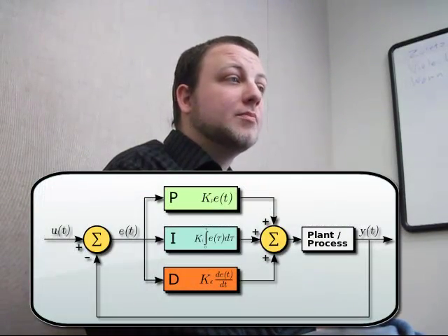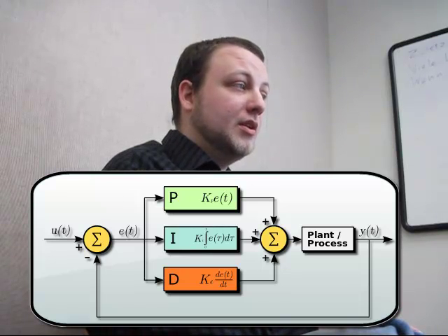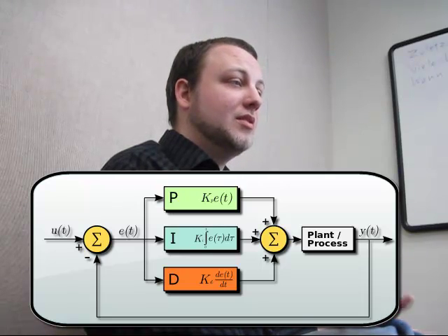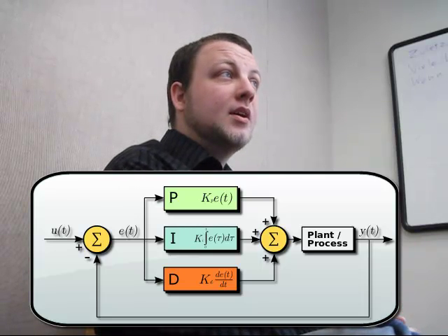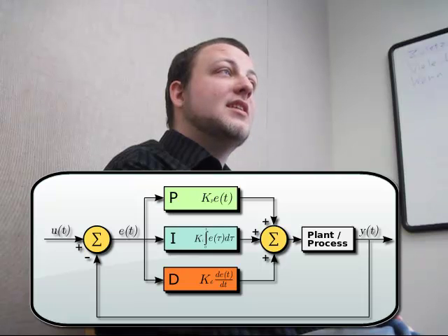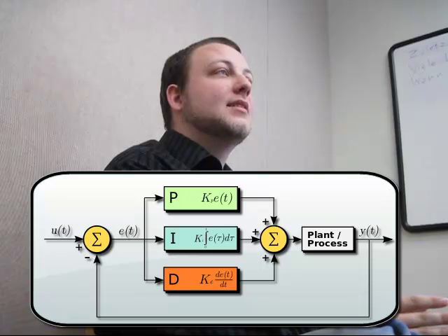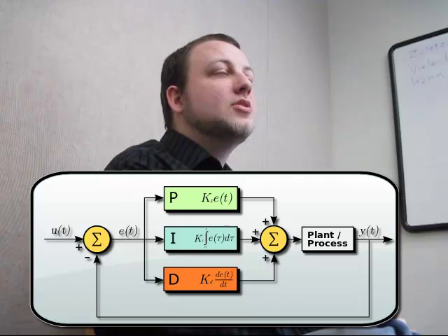The PID control loop is a classic control system that stands for proportional, integral, and derivative. The proportional term is the measured error between the desired location, which is the user input, and the measured location, which is the theoretical actual location of the system that's measured through sensors. The integral term accounts for steady state error, which is the discrepancy between the sensors and the user input, and accumulates the error over time to account for this error.